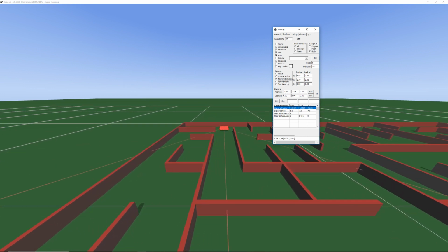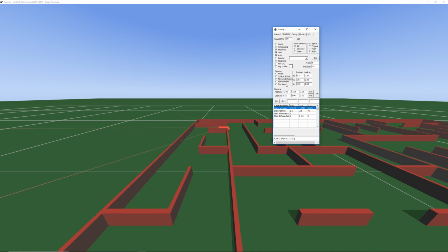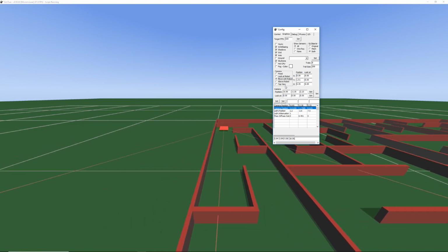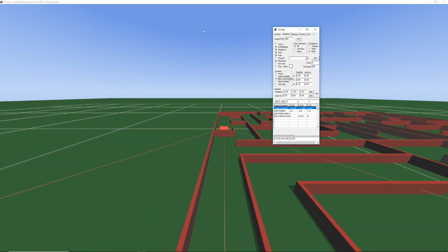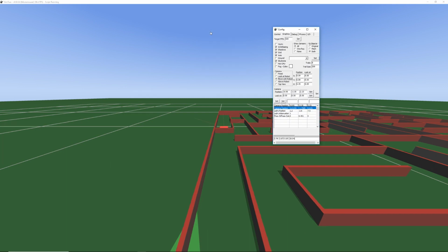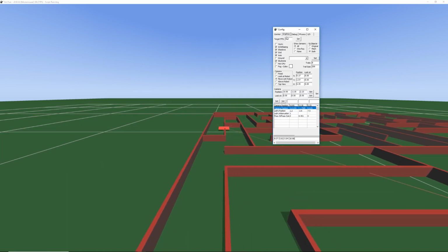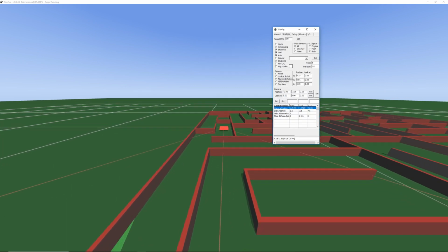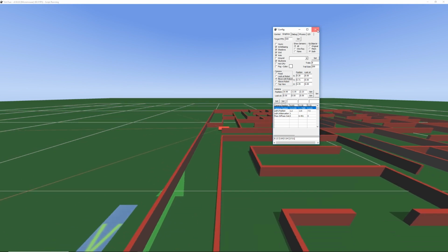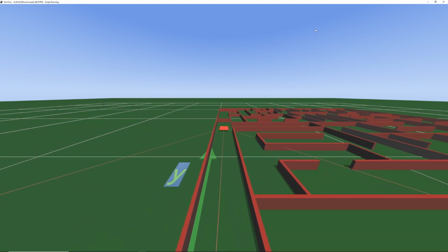So when you launch the application, if you have a dark screen, that's the way to fix it. You right click in the main screen, go to config, go to graphics, and select move with the robot. So I hope you enjoyed it, and if you have any questions, please don't hesitate to send us an email.